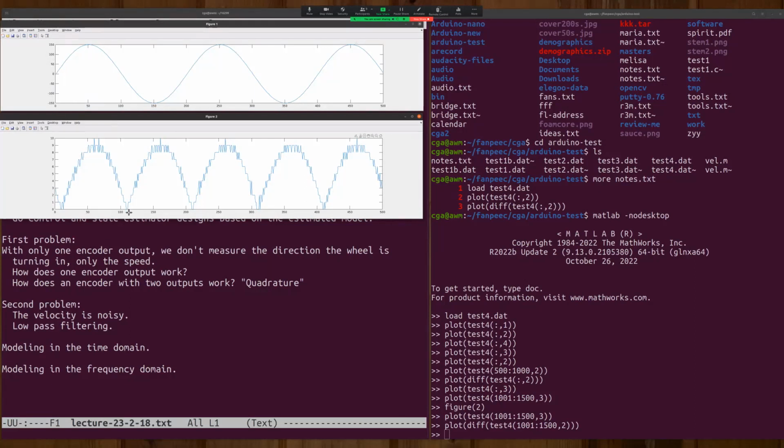And we can ask the question here, what is the command? If I get that just right, I think everybody can agree that this is 110. So I want something in that vicinity. At 110 here, the command is minus 42. So if we say the command's negative means the velocity should be negative, we then say, oh, it's now moving in a negative direction, and the next possible switch point is here.